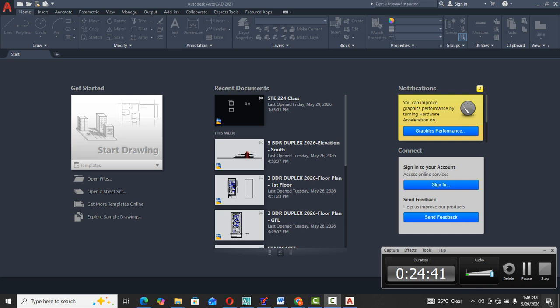If I click on any point, whatever I type against this 496 will make it a radius. But if I want it to be a diameter, I will just type D, capital letter D. I say enter. You see that it has covered the 496.4168, and it is now over.